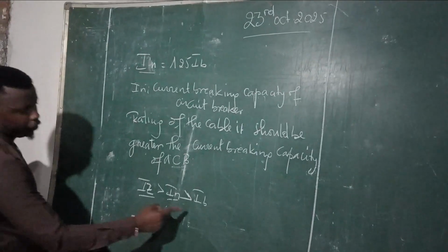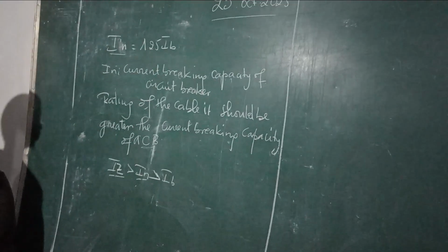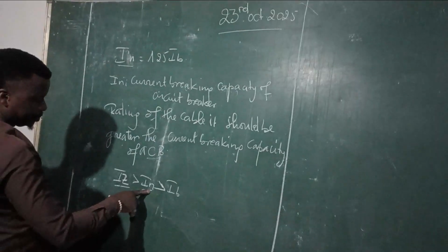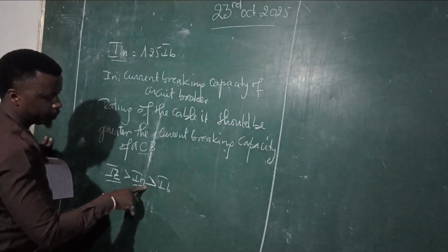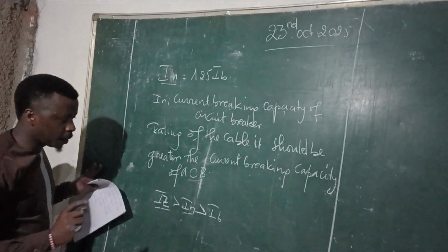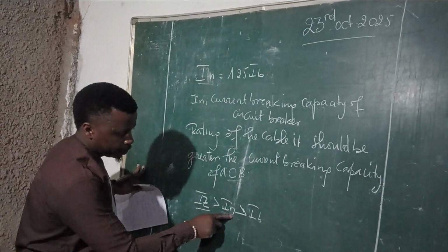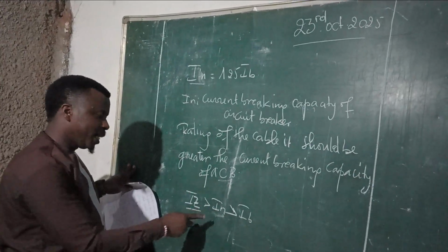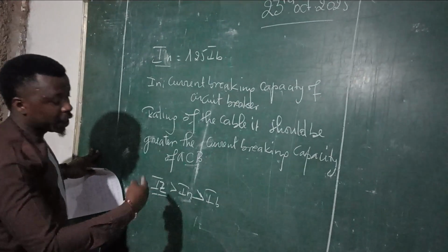Now, why this formula varies and how we can explain it. Let's begin here. This is the design current, the current it draws. But remember, when an appliance starts, it can draw much more current. So to allow it to not trip, this one must have a greater rating, by adding the tripping time based on its technology and its type.